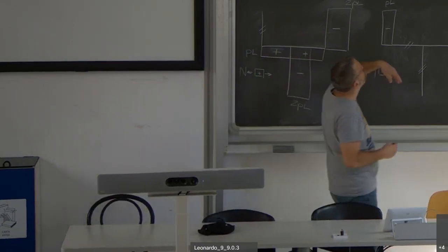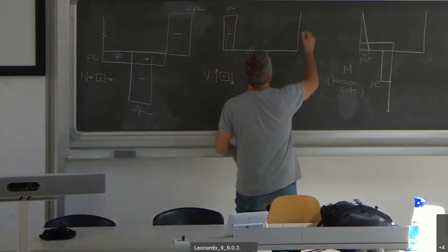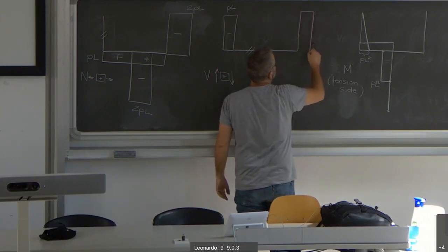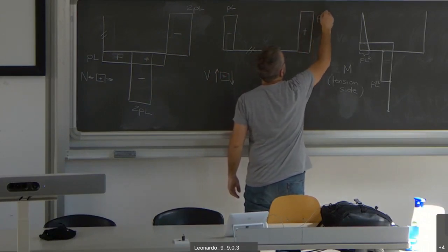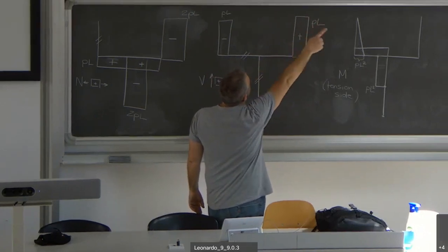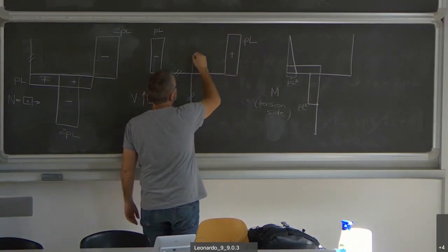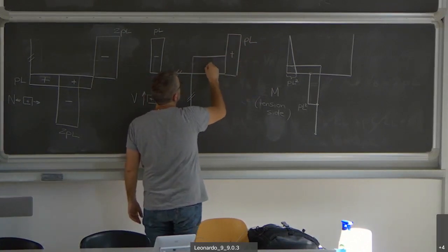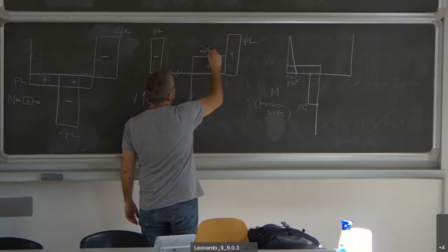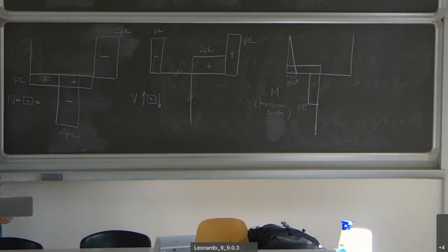This is done. Shear force on the top, PL positive. Horizontal part, 2PL positive. Bending moment. At the top it's 0, there is a hinge.